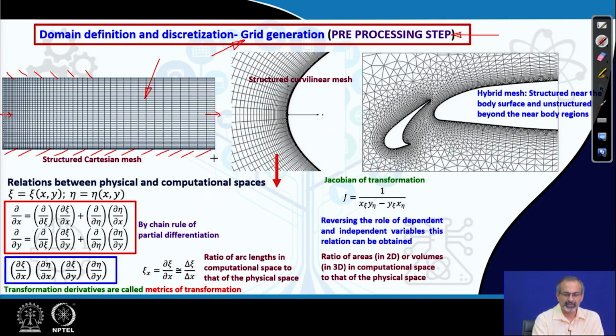But before you do all that, as you can see, we have discretized the domain into a large number of rectangular control volumes, if you look at it from the control volume point of view, or you can also look at it as a large number of grid points. If you look at one of the intersection points, then that happens to be a grid point.